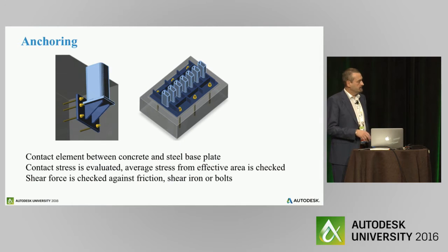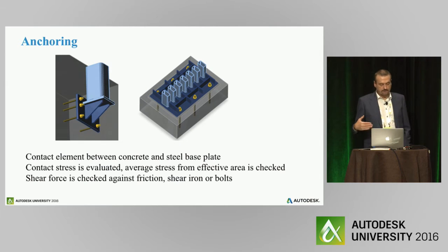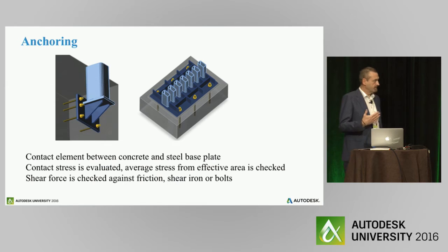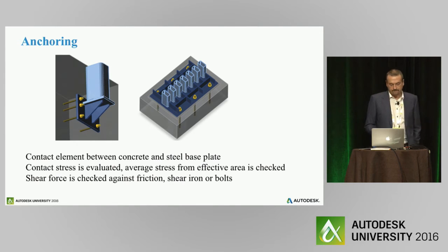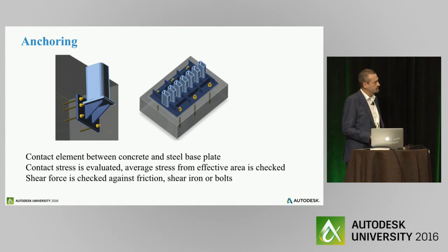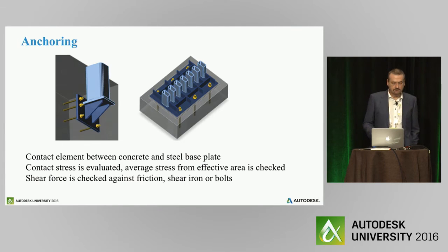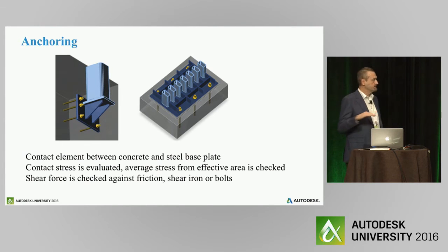The concrete block is calculated like subsoil. In fact, in the same way you calculate buildings on subsoil, we put the model of joint on this subsoil with concrete characteristics. And we can evaluate the contact stress between plate and concrete, calculate average stress from it, and check it according to code.